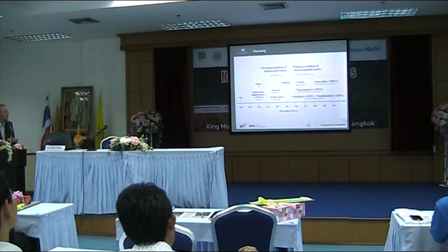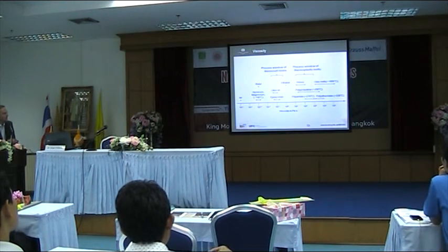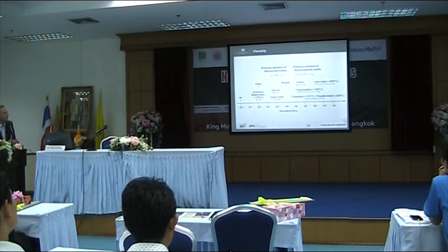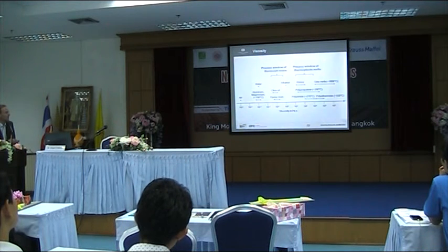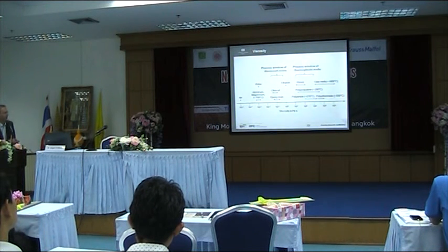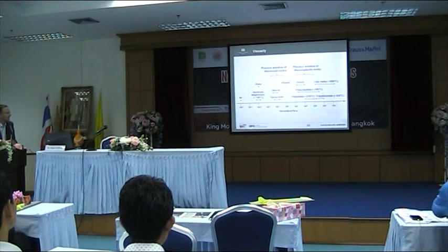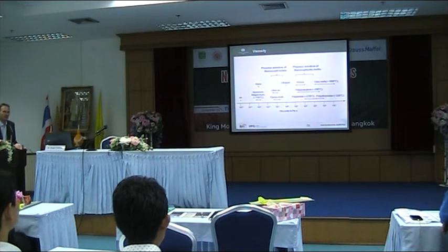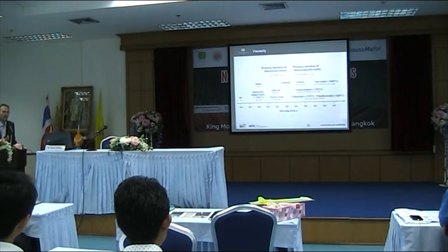You can see here the viscosity of typically polypropylene, polyamide, in processing viscosity, something between 100 to 1,000 Pascal seconds. Compared to epoxy resin, we are below 1 Pascal second, so it's something around 100 millipascal seconds to 500 millipascal seconds. So viscosity means the flowability of the thermoplastic melt.